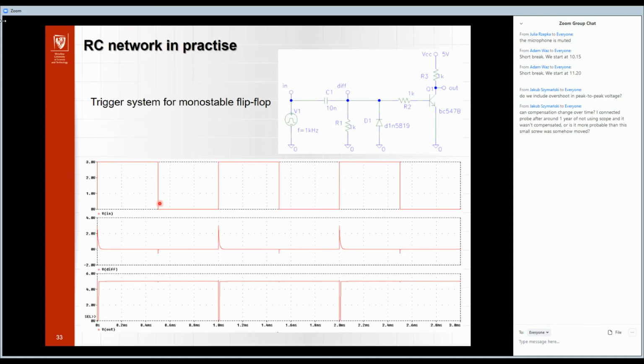So firstly, I draw the signals from the source. It is a pure square signal. And after this capacitor and this resistor, it is a differentiation device. So after this device we see only the spikes here, and the pulse goes up and goes down.